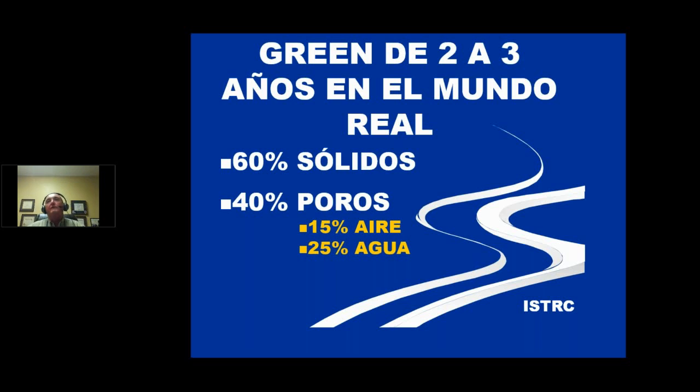The air pores are very important to us because they provide space for root growth and gravitational water movement. So when we look at the infiltration rate, we're measuring the gravitational flow. And then it also gives us the space where our oxygen is. Our water pores are very important to us because that is where our water balance happens to be.